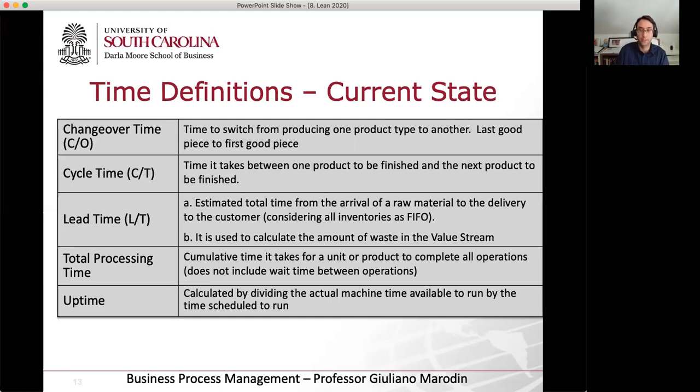So we're looking at the process, let's say someone assembling something, someone cutting something, or equipment doing some machining, or a press, pressing and molding some metal sheets, whatever it is. And then one product gets out, you start your clock, the next product gets out, you stop your clock. So the time between products, without any waste, right? So the equipment is running, doesn't stop in the middle, it doesn't have any movement. It's the time that your process is doing the job.